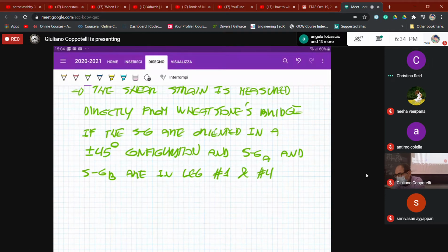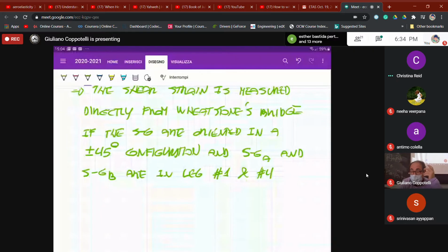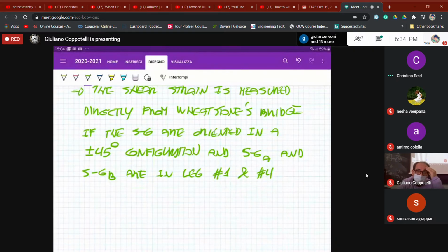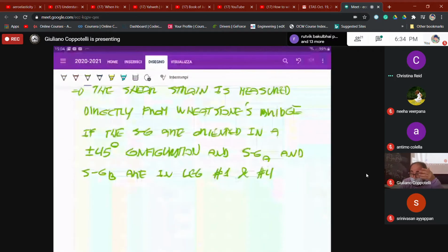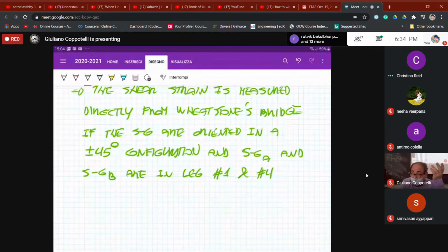Some angle is the angle from the given reference frame in which we are having the minimum or maximum normal strain, okay? Because that comes from a minimization of the strain with respect to the orientation angle, okay? So you can find both a minimum or a maximum.